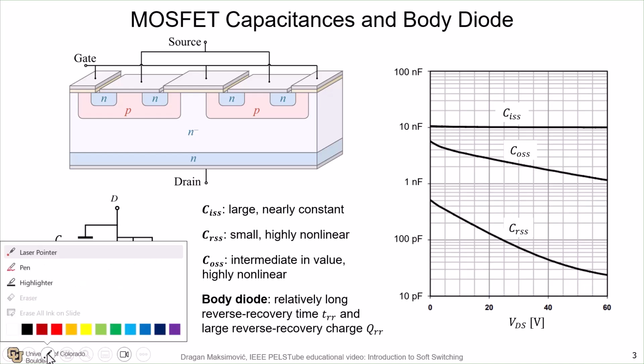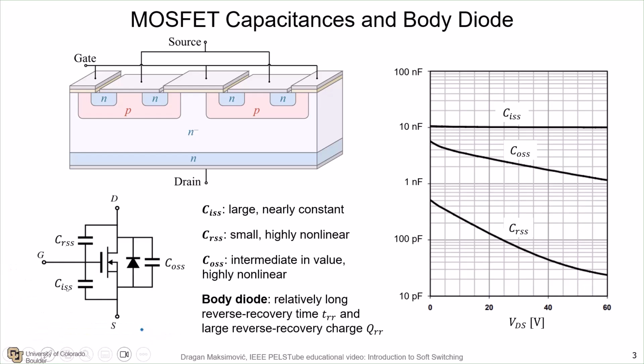In addition, importantly, the device contains a built-in body diode. That body diode is effectively present between source and drain terminals, and we show it explicitly here, understanding that you cannot just take that body diode out, it is part of the device itself.